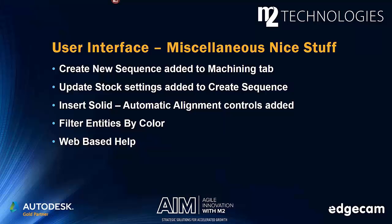For those of you who insert multiple solids into a part session in Edgecam, maybe build an internal assembly or something like that, the automatic alignment controls have been added to the insert solid command. So this is great. It saves a step. In the past, we might have to insert the solid, and then we might have to go reposition it, where now we can insert the solid, configure the automatic alignment, and get both actions done in one shot.